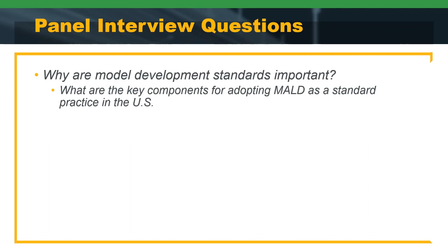And so for me, the key components are everything that you need to truly be able to understand the information. So you're going to have a BIM manual, or a model development standard. It's basically your CAD manual on steroids. It's going to cover how to organize the information within the file in the same way that the CAD manual did. So instead of having tables of 250 different levels and what line style and line weight and what have you, it's going to have the object version of that, the BIM version of that. So taking it away from lines, arcs, text, colors, and things like that, and into object-based. It's going to have your naming conventions and all of that.